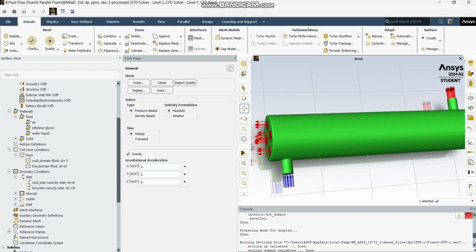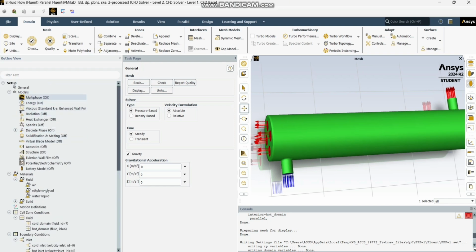What's necessary to do is to define boundary condition. As you see here, with the blue arrow it's the inlet, and with the red arrow it's the outlet. So for us it's important to define the boundary condition. For boundary condition we can use mass flow, velocity inlet, pressure outlet. There is more options to use. The more important thing is using the models. So I will discuss a bit about this option.